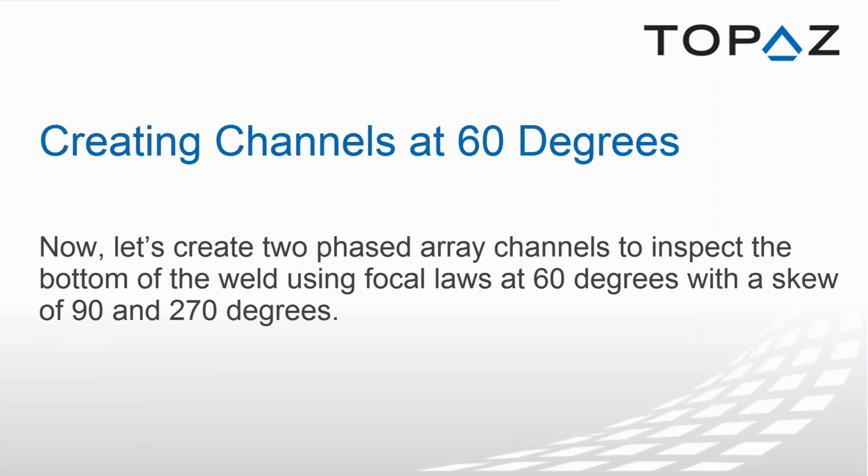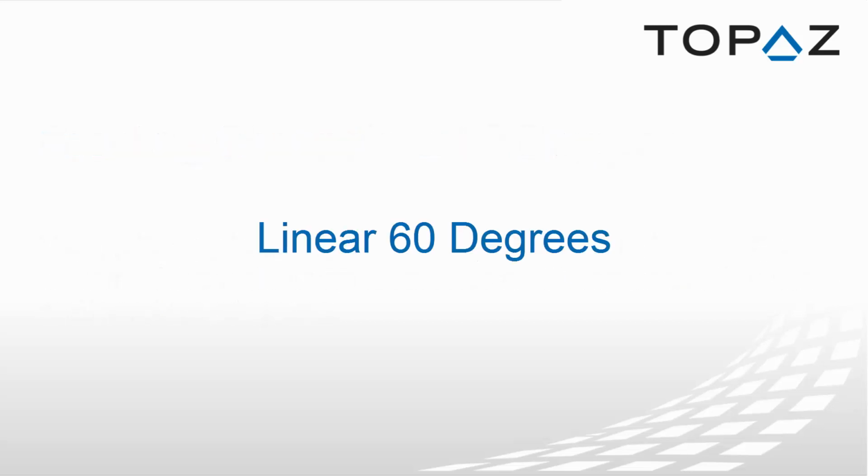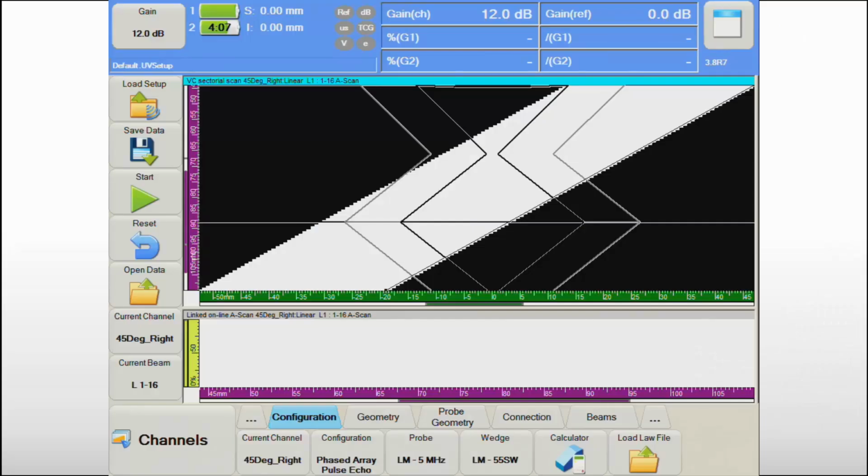Creating channels at 60 degrees. Now, let's create two phased array channels to inspect the bottom of the weld using focal laws at 60 degrees with a skew of 90 and 270 degrees. Our next video will be on linear at 60 degrees.